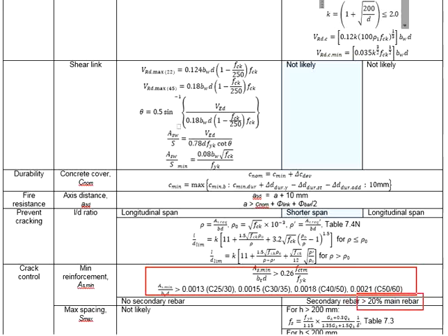Whatever reinforcement bar you have calculated in the transverse directions to the main reinforcement, you make sure that the requirements for the AS-min is fulfilled, and you make sure that at least 20% of the bar areas is applied.